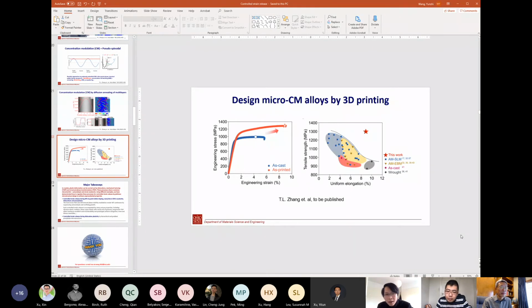Have you thought about combining the way we can regulate the microstructure with tailoring the composition, because that affects the stacking fault energies, and that would affect the TRIP and TWIP behavior? Have you thought to combine the two approaches together to increase flexibility in controlling the microstructure and also manipulate TRIP or TWIP behavior in the titanium alloys?